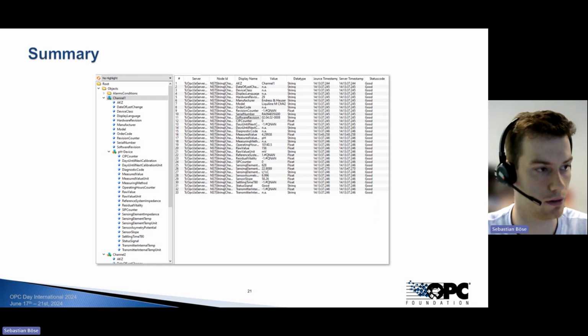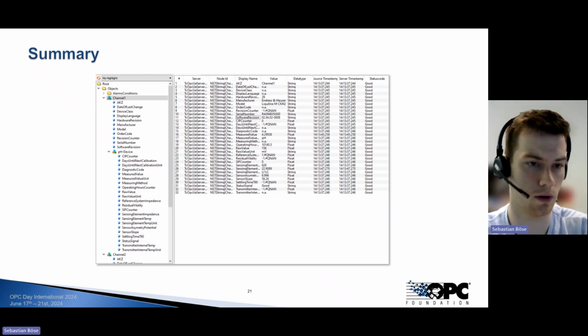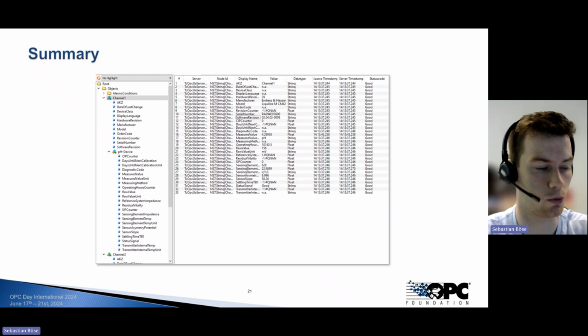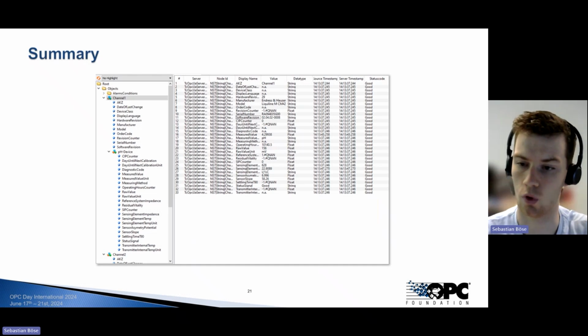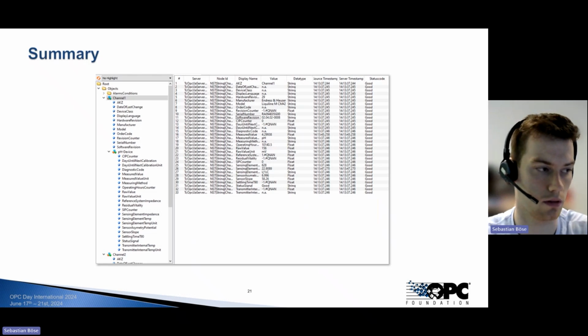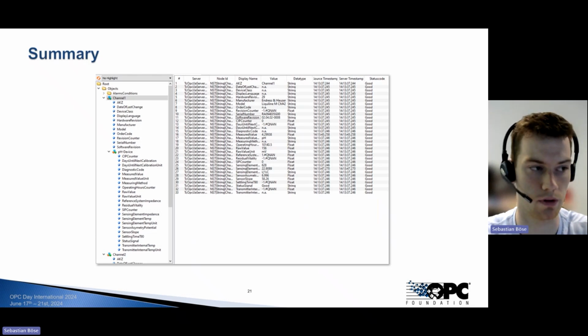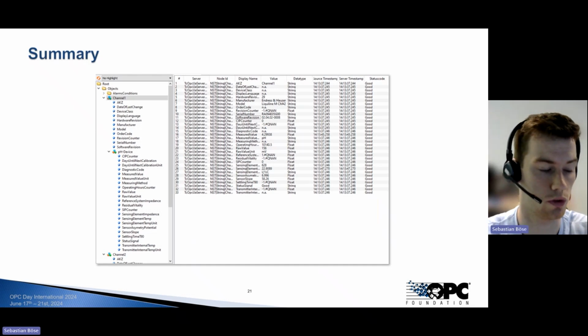So this is already another screenshot, for example, from a Liquiline here, which we connected through the HART protocol. And the main point is that we also want a standardized way of presenting it in the OPC UA server. So there are two options. The easiest option would be that we just put all the variables that we have in the PLC in our controller to OPC UA, so that the end user or the customer can just access the whole set of data and needs to search for each and every parameter for himself. Like I said, it would be the easiest one, but we chose another one.